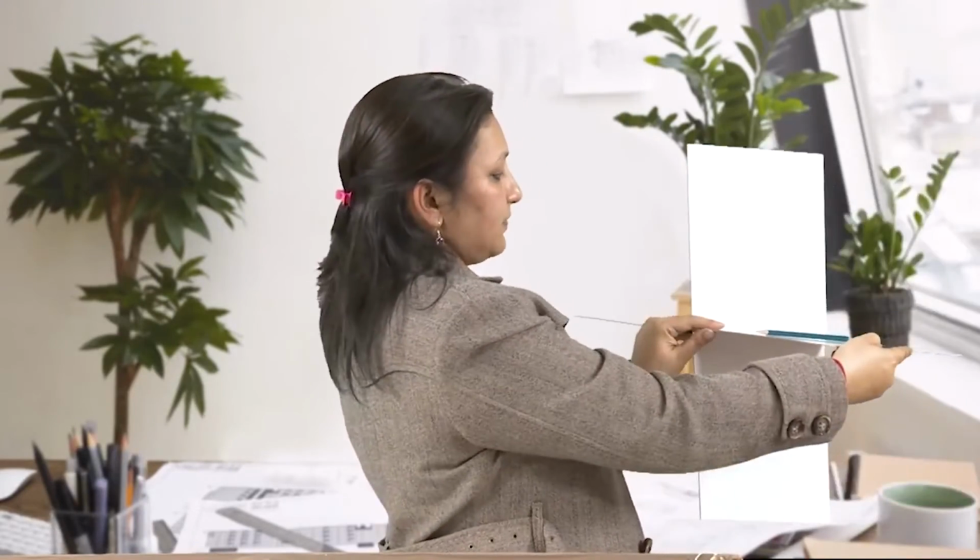Now, if I am seeing it from the side elevation, what would I see? This line is actually perpendicular to the side plane. So, if I see it from the left hand side, so I am holding the quadrant like this and I am seeing it from the left hand side. So, we see the front from here, and if I see it from the left hand side, the projection will be cast on the right hand side, and all I will see is a point which will be in XY. So, it will be projected and this is an elevation. So, we will be seeing this projected in XY.